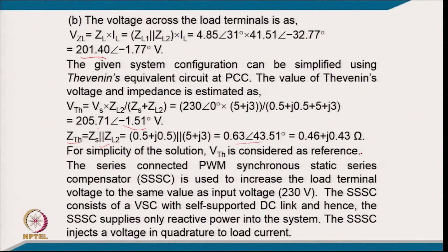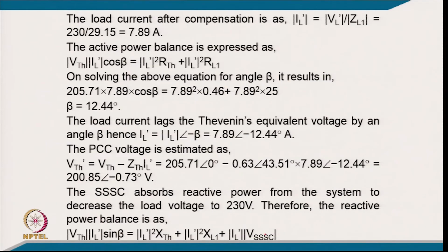For simplicity, the solution we have considered as a reference, and a series connected static synchronous compensator is used to increase the load terminal voltage to the same as the input voltage of 230 volt. So, SSC consists of a VSC with a self supporting DC link, and hence the SSC supplies only reactive power into the system, and SSC injects the voltage in quadrature with the load current.